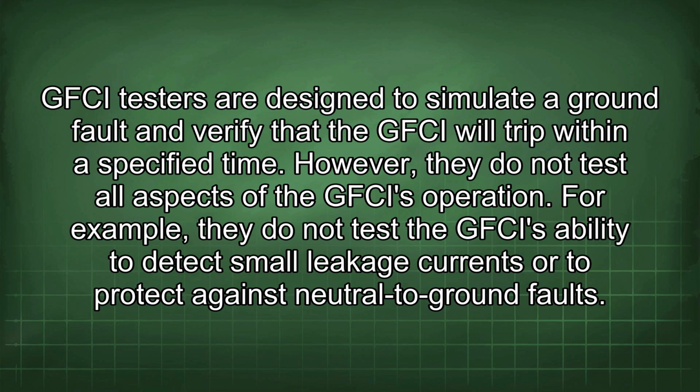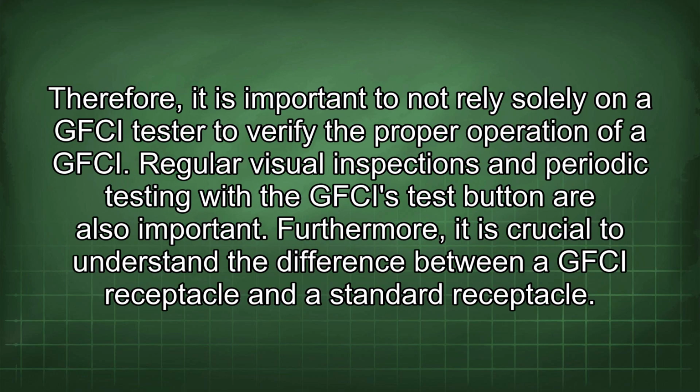For example, they do not test the GFCI's ability to detect small leakage currents or to protect against neutral to ground faults. Therefore, it is important to not rely solely on a GFCI tester to verify the proper operation of a GFCI. Regular visual inspections and periodic testing with the GFCI's test button are also important.